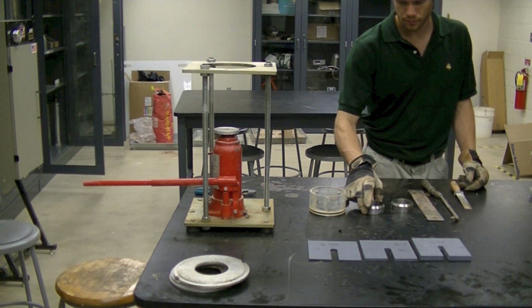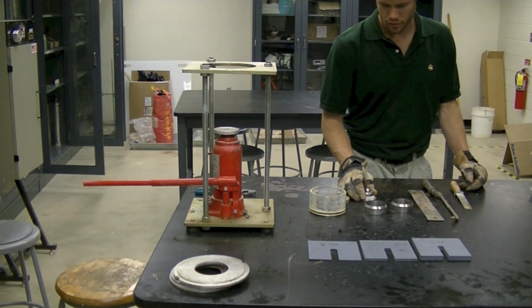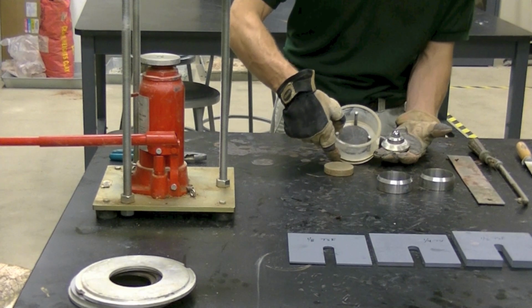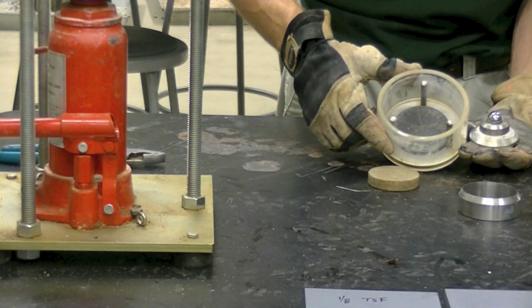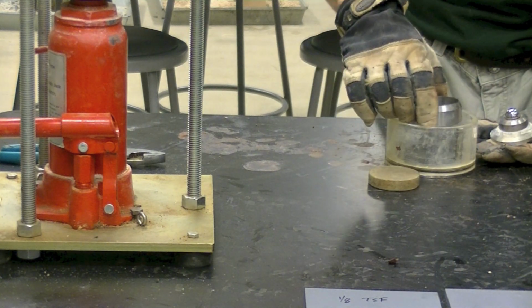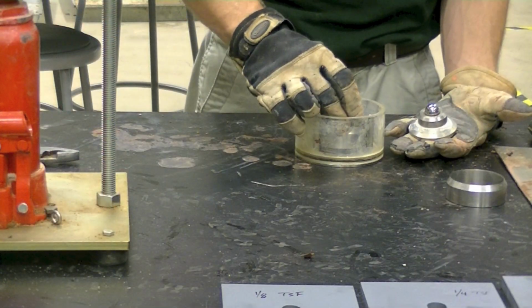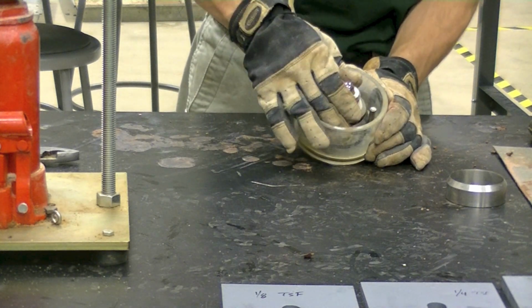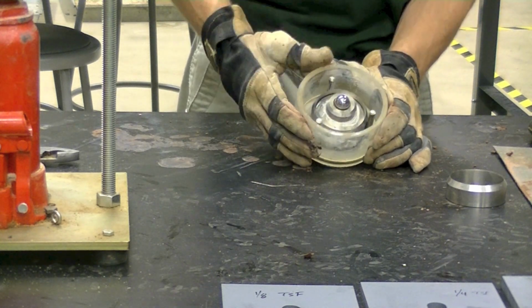Consolidation rings with beveled edges. The ball and top platen, setting cup with a porous stone at the base. The sample fits within the ring's inner volume and sits on top of the porous stone, then porous stone above, and finally top platen and ball. Load is applied to the ball so that a uniform load is distributed across the area.